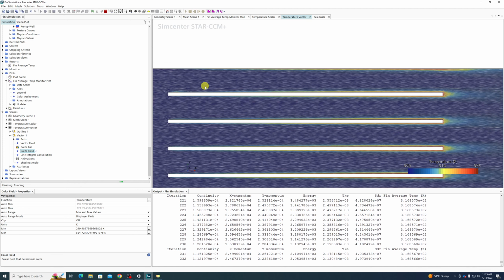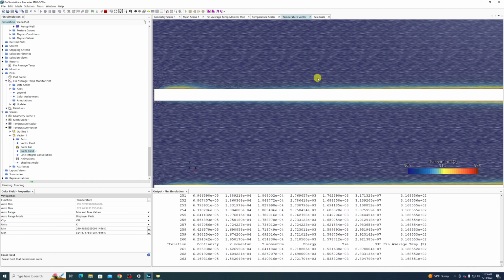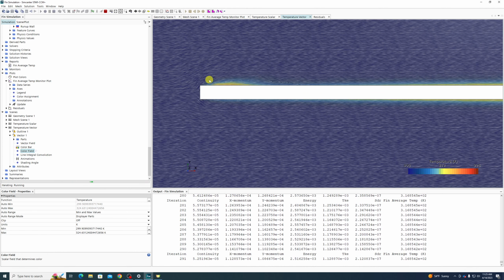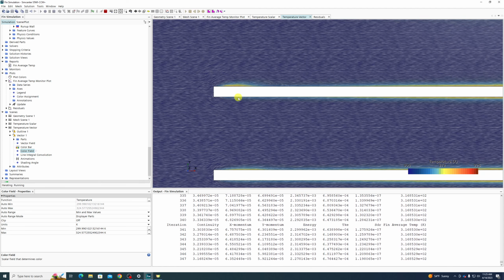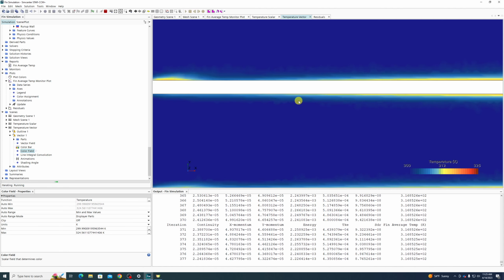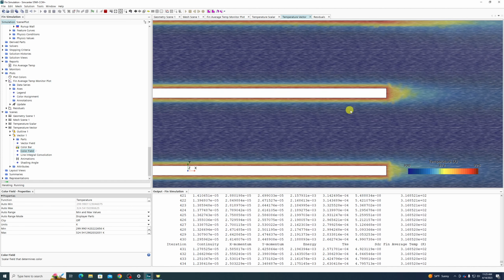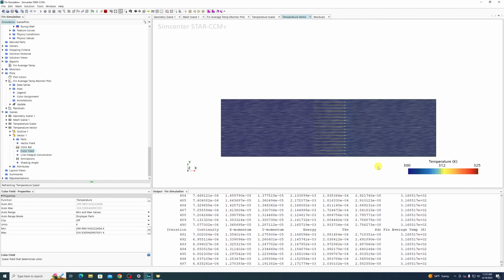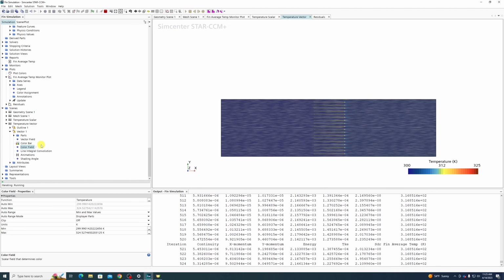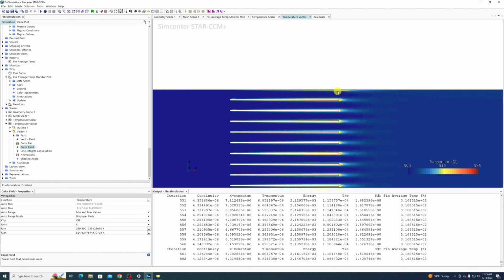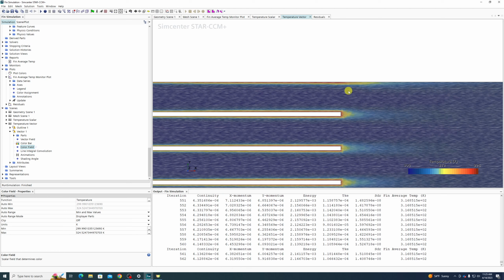There we go. So you can actually see, here we have almost a tiny separation bubble at the very edge of the fin. But by and large, you start with a relatively thin thermal boundary layer, and it grows over the course of this fin until it reaches the end and it flows downstream. So we can do some basic math potentially to verify this, but at this point, this should be giving off exactly 2,000 kilowatts.